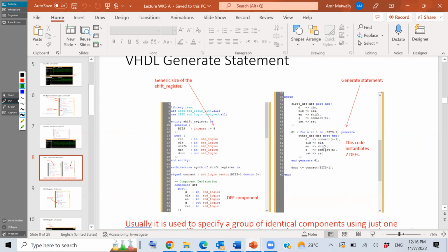This is repeated for n from 1 up to 7 bits. 8 minus 1, that's 7. In this generate, I am repeating this 7 times plus the first starting one. That makes it 8 D flip-flops. When I end with those, I am ready to go to D out.